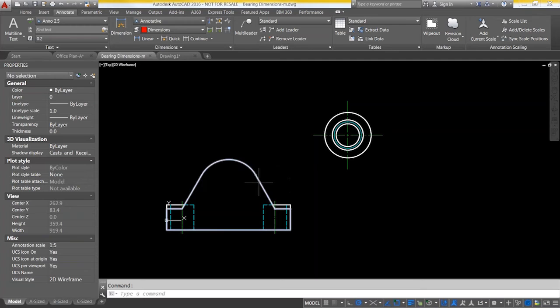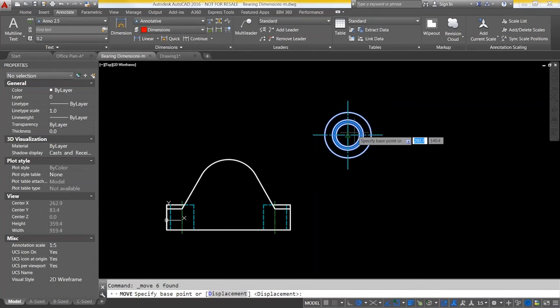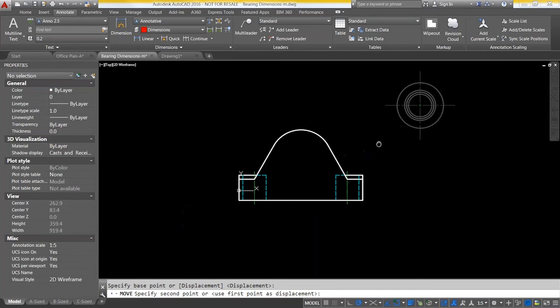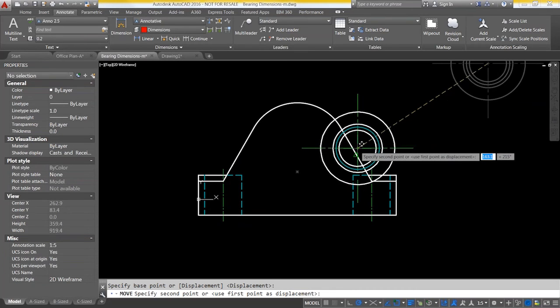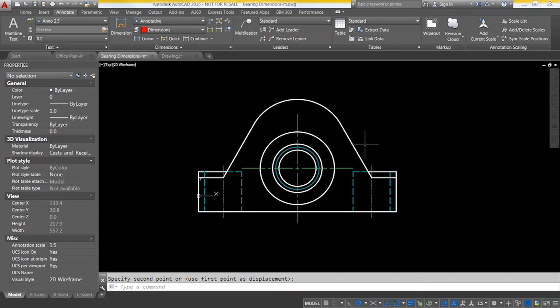Now, I have a shape here, and I've got a cam bearing system, and I want to apply this, and I'd like it to be in the middle of this shape. So more specifically, I'd like it to be in the geometric middle of this shape. So let's see what we can do. Just going to select it, right click, use the move command, pick a base point. Now watch this. I'll zoom in here slightly. I'm going to hover over the edge. Now, do you see that little asterisk that has appeared? That is the geometric center of this shape. So I can literally snap it onto there. Very cool, I think.